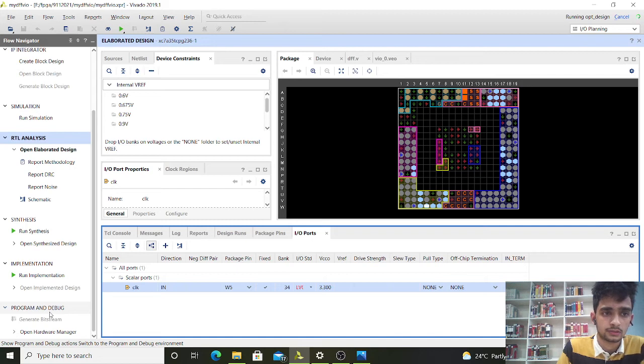So you can check the reports, timing reports, and all the reports like constraint and all these things by doing separately after the synthesis, before the synthesis, after the simulation. You can check our schematic also of T flip flop, elaborate the design.